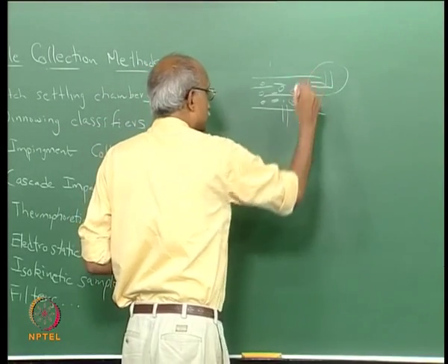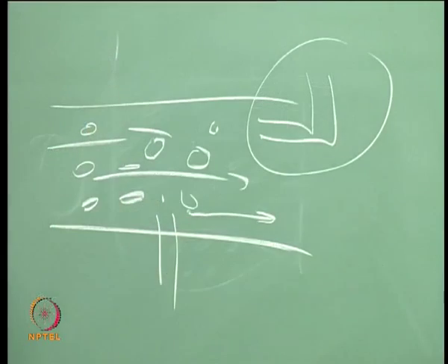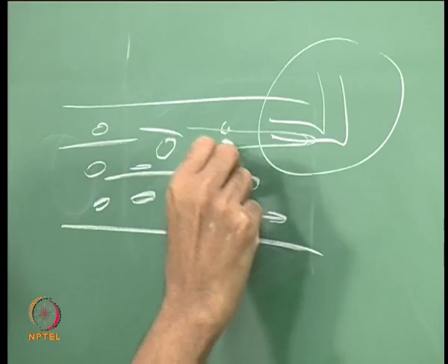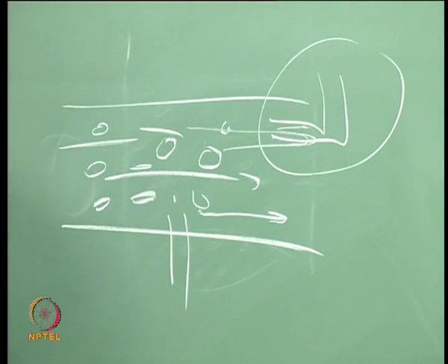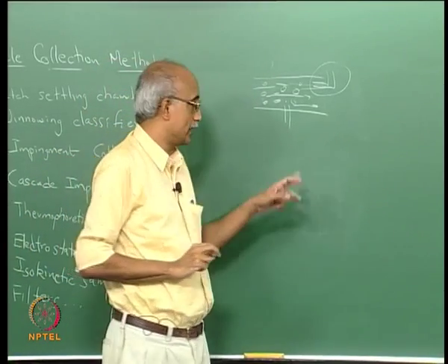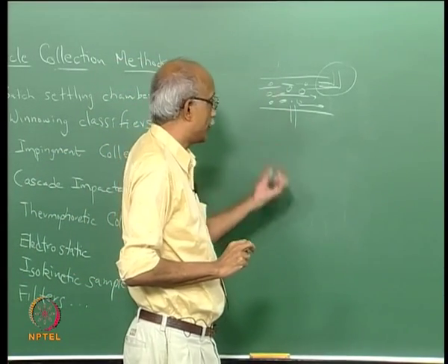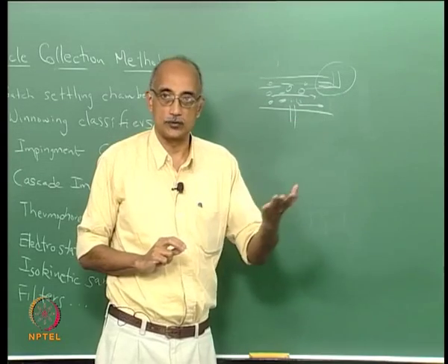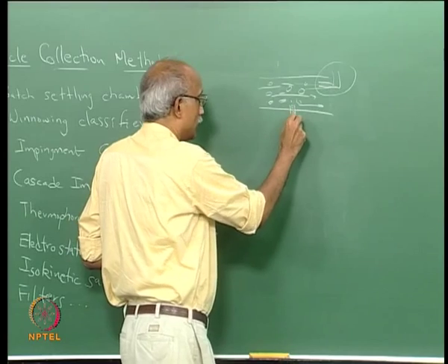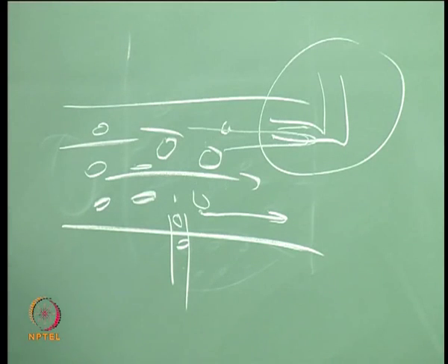This one, because here the fluid and the particles are going to be flowing through your collector essentially at the same velocity and same direction as in your process chamber, whereas here you are actually collecting particles orthogonal to the flow of the fluid. So, the particles that are going to be collected in this case are those that do not follow the streamlines, right.